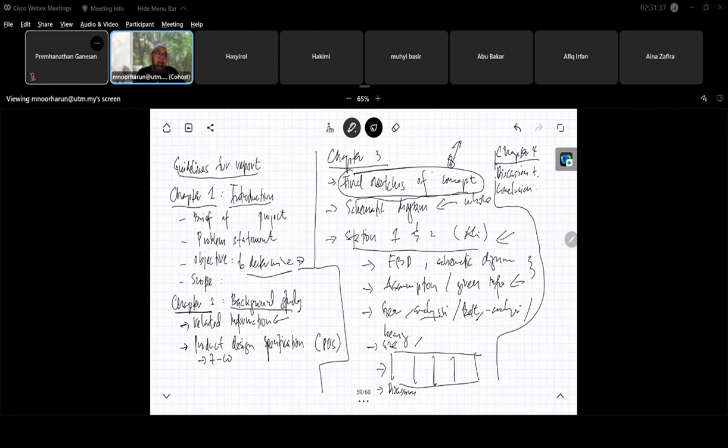If the given dimension is very small, the part with the proposed dimension cannot support the load. So based on your analysis, it will fail. Then you will either change the material to increase the Young's modulus, or change the dimension, or change the design.